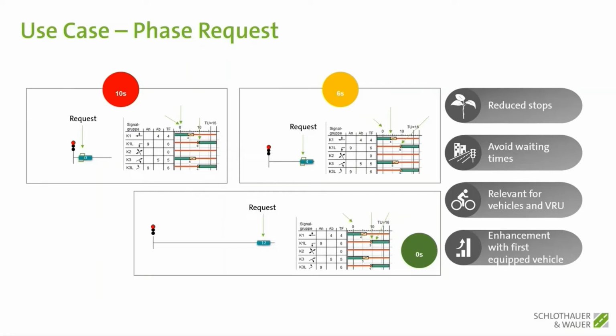And now there is some new technology. The CITS information means that you can track the car, and if the car is as close to the intersection that you decided to use that information, you can bring it into the control. So we have the request here because we are 12 seconds before the stop line. And then we have our intergreen, and then we will have directly the green when the car reaches the stop line. But just to make that clear, in that case, we have a car which goes directly to a red signal, and so the car will decrease its velocity.